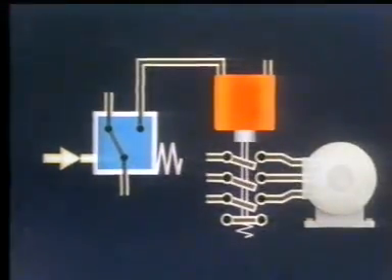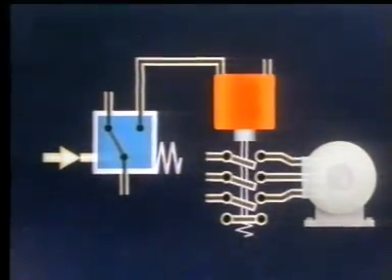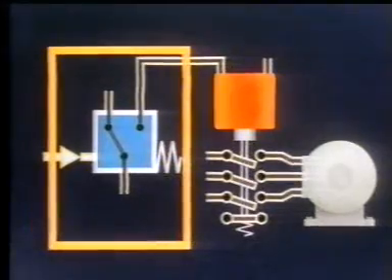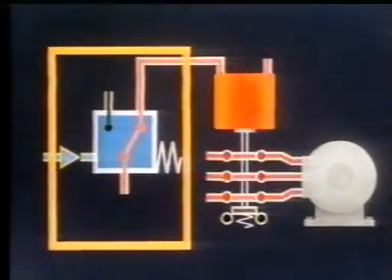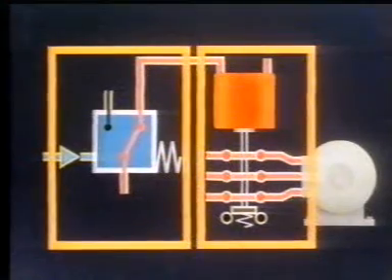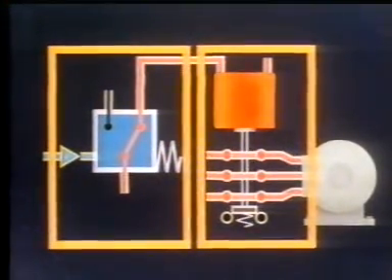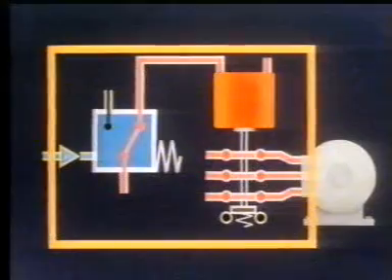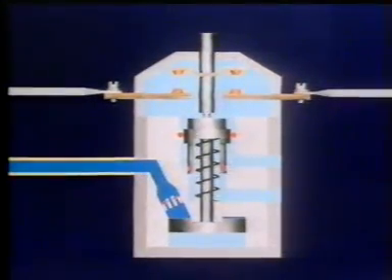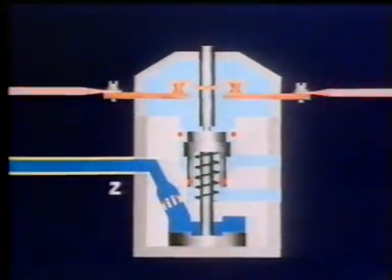Pneumatic electric transducers, contactors. If a motor is to be switched on by a pneumatic circuit, a pneumatic electric transducer is needed. The motor contactor is actuated by means of the switch. A pneumatically operated contactor thus combines both functions in one device. This is how it is constructed. By applying compressed air to the piston via Z, the contactor picks up and closes the contacts.